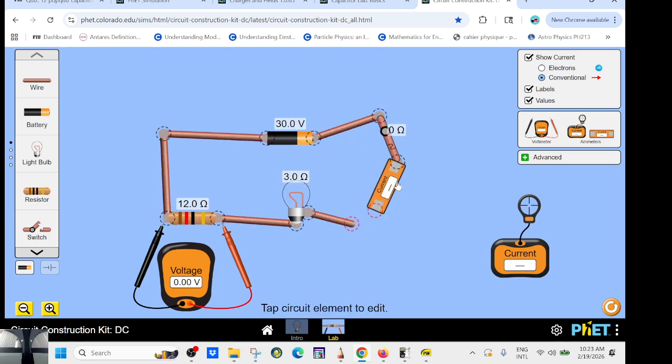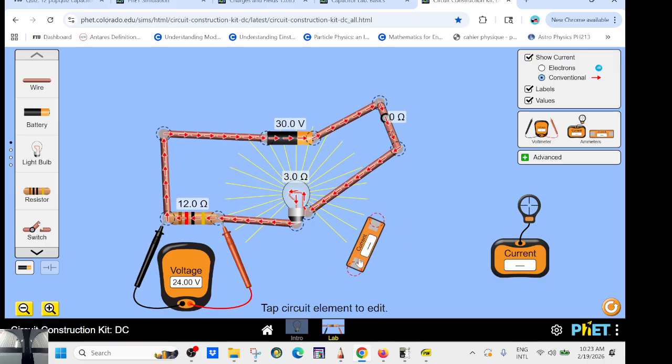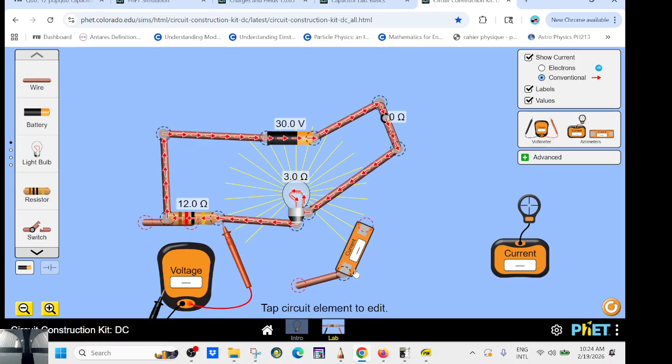which could be very tricky, because some students don't listen. That's a student thing, right? I've seen that so many times: they will put the multimeter to measure current as a short. That will be very bad because you are making a short. The current wants to take the path of least resistance because it's lazy.